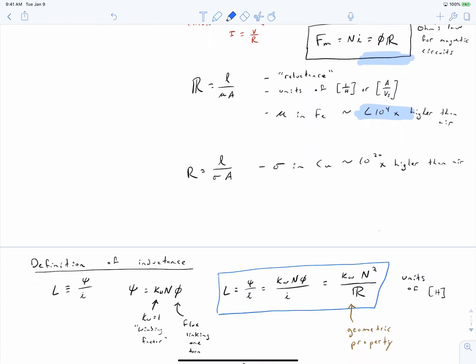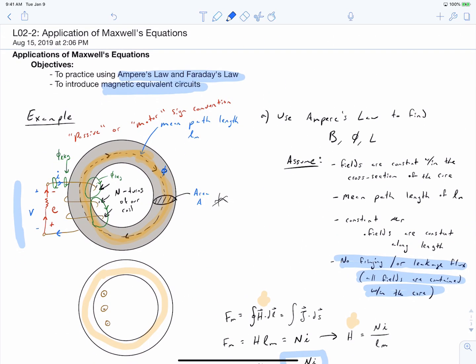So we have two pathways for studying the magnetic fields in our structures. One is, as we've discussed in this video, analytic derivations based on simplifying assumptions. So we make enough assumptions so that we can actually solve Maxwell's equations. However, this comes at the price of accuracy. We're also going to be solving the magnetic fields in the cross-section of our motors numerically using something called the finite element method. And that will be covered in a later video.